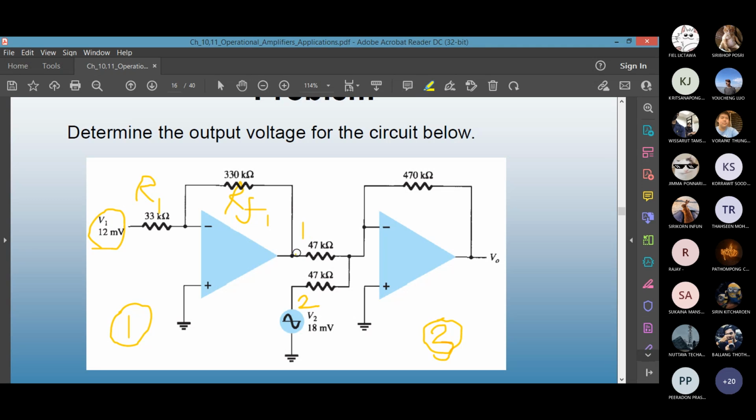So at this stage, if I put a voltage probe at this stage, let me clear a few things. At this stage, you are getting minus 120 millivolt. I can write that, mV. This one, still focus on the first one. Again, it passes through an inverting summer.